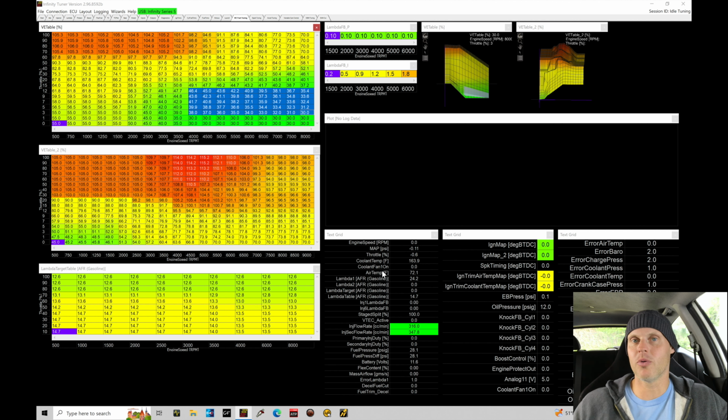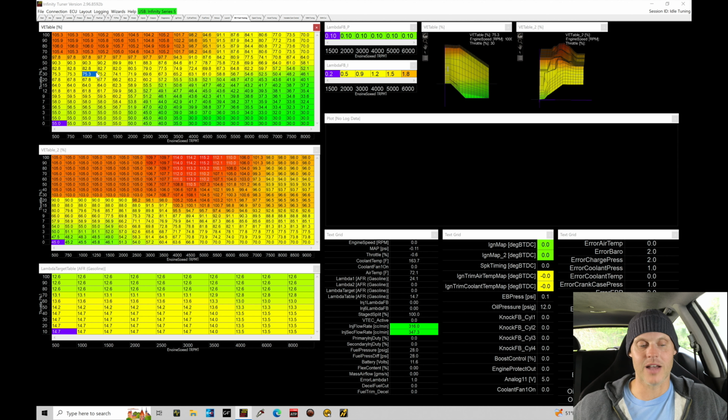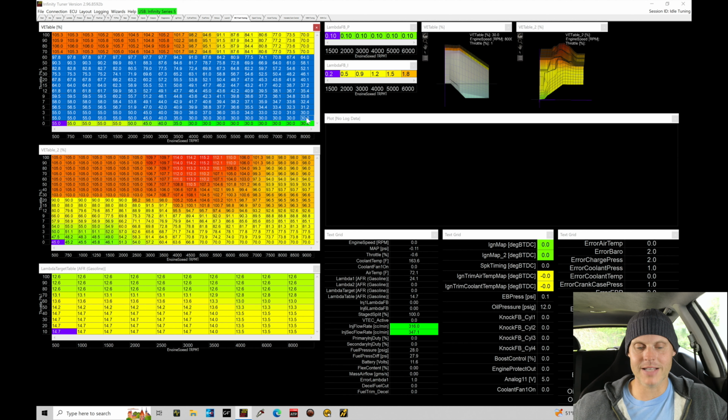And this is going to take a couple driving revisions, driving cycles to get this nailed down, but we should have at the end of this a solidly dialed in VE table from, let's just say, 60% throttle and below. The last bit of the table here, 70% throttle and higher, we're going to be dialing that in the next tutorial, looking at doing our wide open throttle low cam non-VTEC tuning. So we're just focused on the low cam operation, not on high cam at this point.